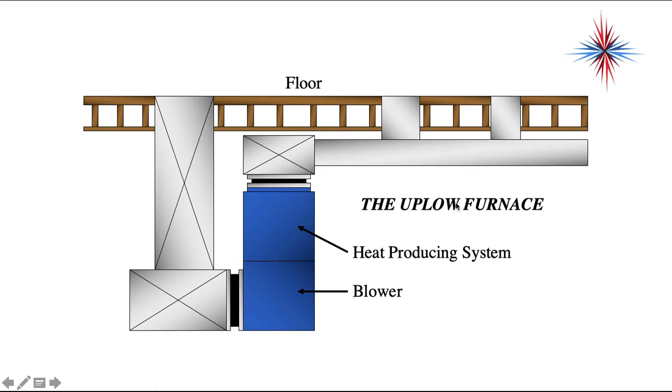Now, this same configuration can be used again in ranch-style construction that we see a lot in the southern part of the country, where we have a return duct or a return grill right here. This is in a closet someplace. And then this is the attic that we run our ductwork across the top of and come down. If there's air conditioning connected with this, there will be an A coil sitting on top of this, between the heat exchanger and the plenum.